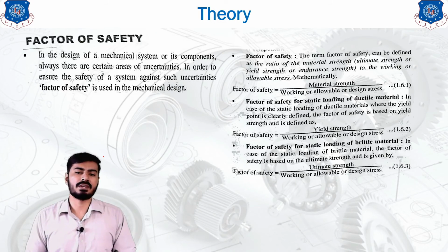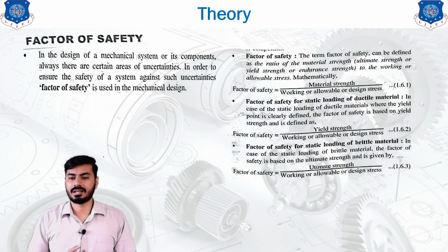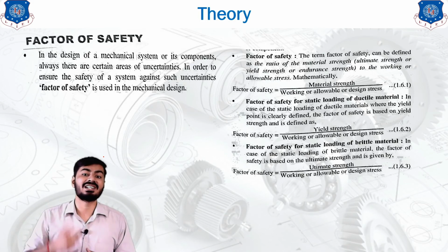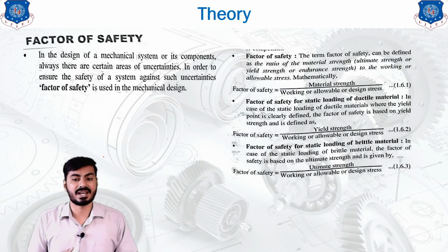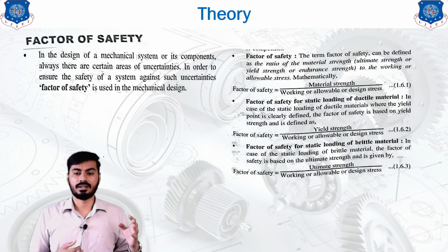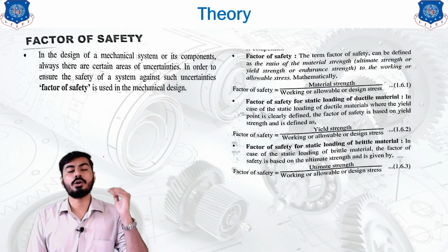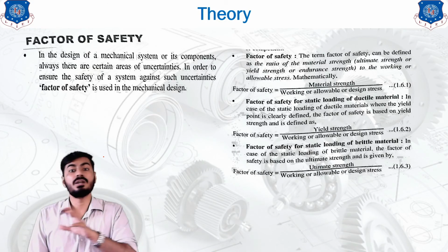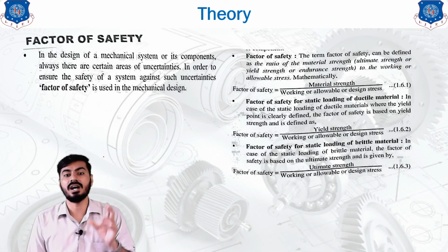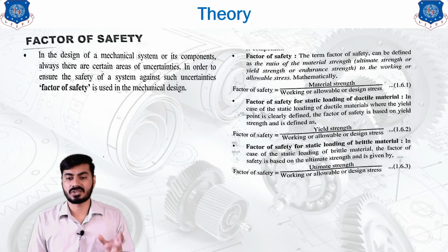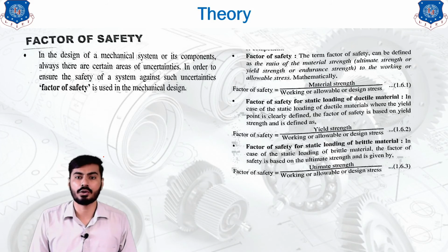So the factor of safety for static loading of a ductile material, where the yield point is clearly identified or defined, based on the yield strength can be defined as the yield strength upon working stress. And similarly, for static loading of a brittle material, where the yield stress is not defined, you will continue this equation with the ultimate strength. We will not utilize the yield strength because it is not clearly identified or defined.